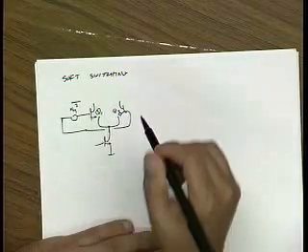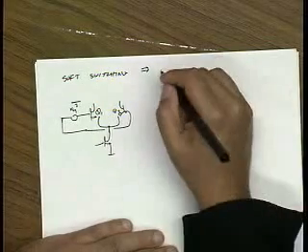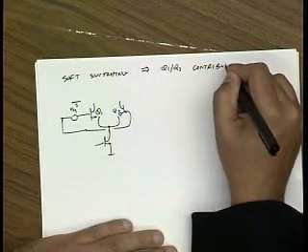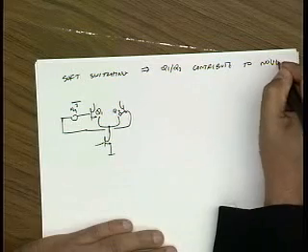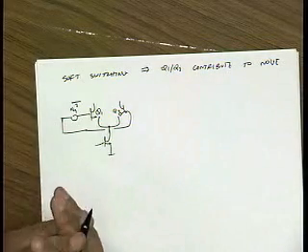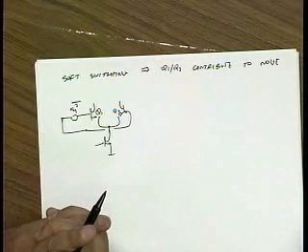So for soft switching, the switching pair contribute to the noise. So that's why we like to have a very large LO swing so that we minimize what we call the on time of both transistors.